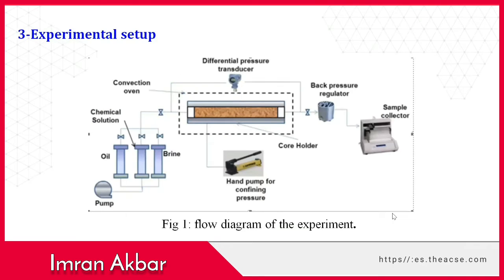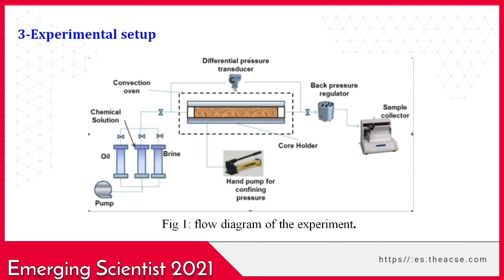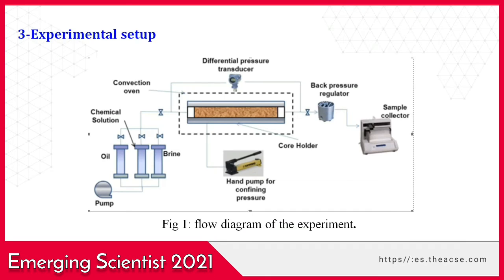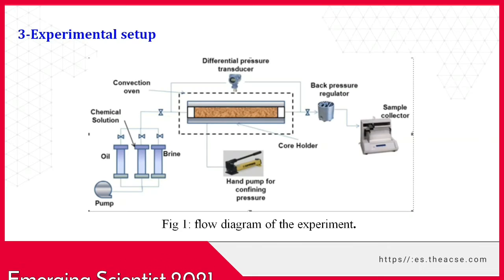This is the equipment of the sandpack. Sandpack is used for displacing oil. The sandpack tube is packed with different sand sizes. In our case, we use a sand size of mesh 120. When the sand is filled in the sandpack tube and saturated with water and oil, we inject different chemicals into the sandpack tube and test the different parameters of this experiment.